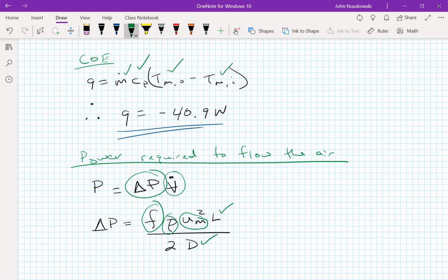So we'll start with the easiest one, density. So we can get density in tables A-4 or ideal gas law, with pressure over RT. And we get, if I can find it, 10.95 kilograms per meters cubed. All right, so now we got that.